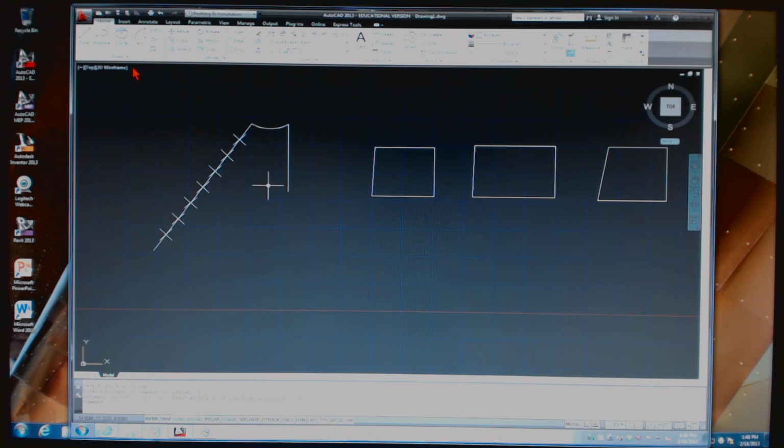It puts an X everywhere where you should be putting your line. So, for example, if I had a line that looked like this that needed to go equally all the way up that thing, the only way you can select the point that it just put on there is you have to have your node, N-O-D-E, OSNAP turned on.